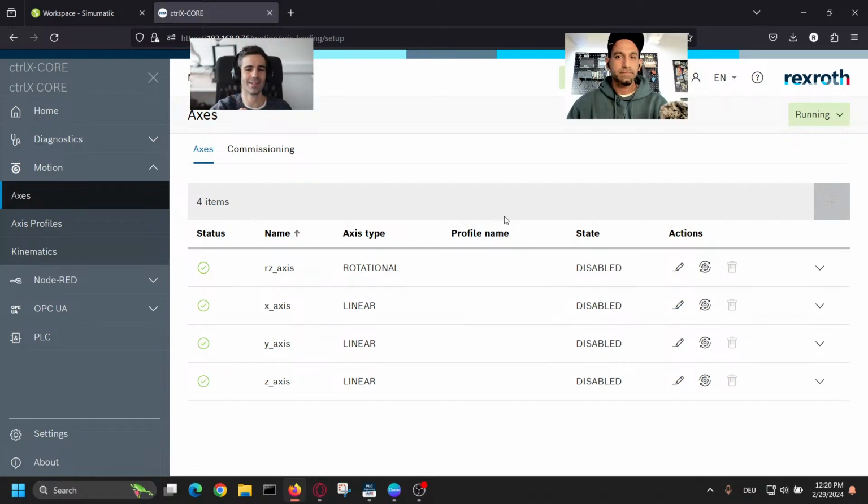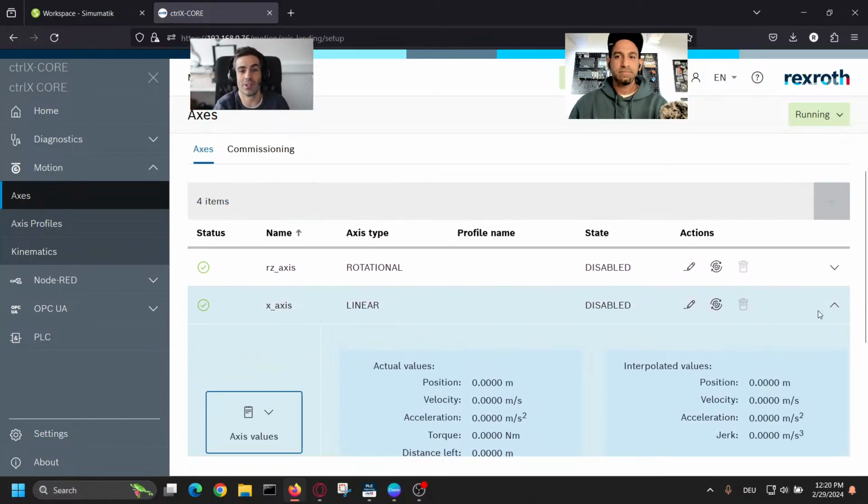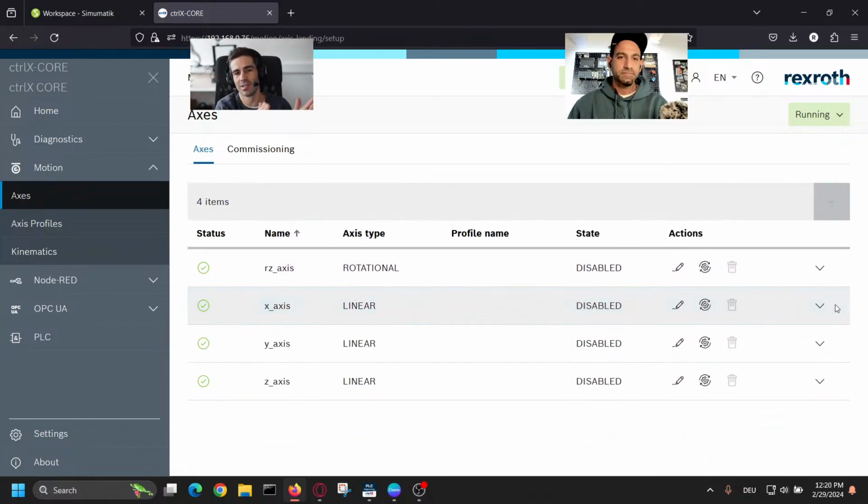You could command an axis to a position or rotation that physically is not possible, but your program wouldn't say anything. But if you can limit this motion in the model and get the feedback from the encoder, from the model, actually we could trigger an axis movement error, telling, okay, the set point says 1.2 meters, but the encoder is stopping at 0.8. We will not get the feedback right now, but if we have a closed loop, we can get the feedback. So it's something that can be done.